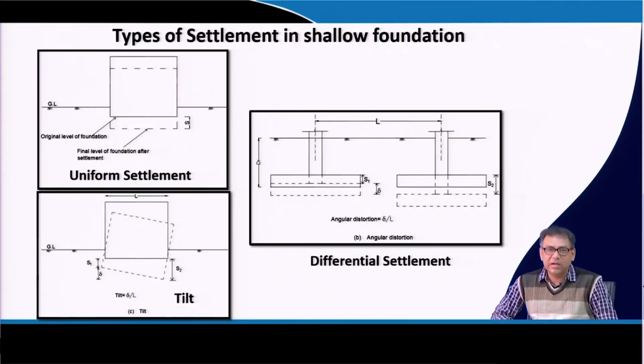If the design load is different in different columns and that difference is significantly high, you have to go for the other two checks also. And if the soil parameter variation is also significant.